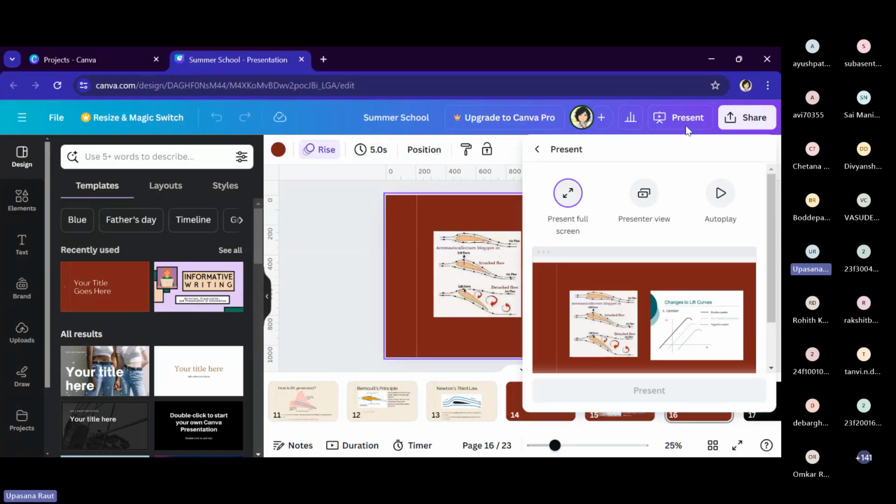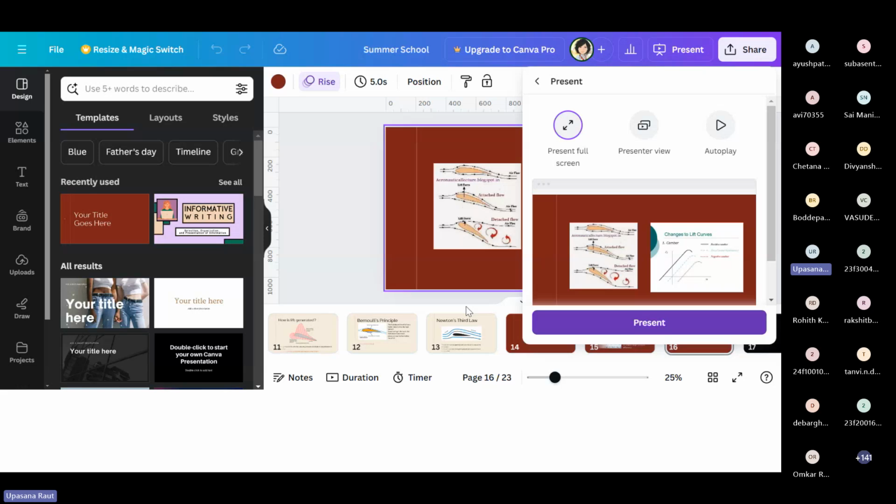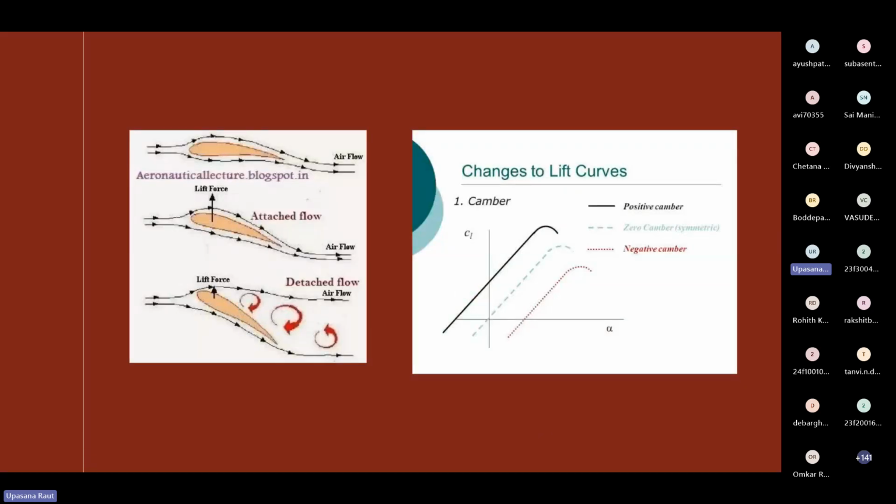The more bent the airfoil is, the more bent the airflow would be, right? Because the airflow will pass along the surface of the airfoil. If the airflow is more bent, it needs to travel a greater distance, so it needs to have a higher velocity. And if it has higher velocity, according to Bernoulli's principle, it will have an even lower pressure. So the lower pressure would create a larger pressure difference, and as the difference increases, more lift force would be generated.